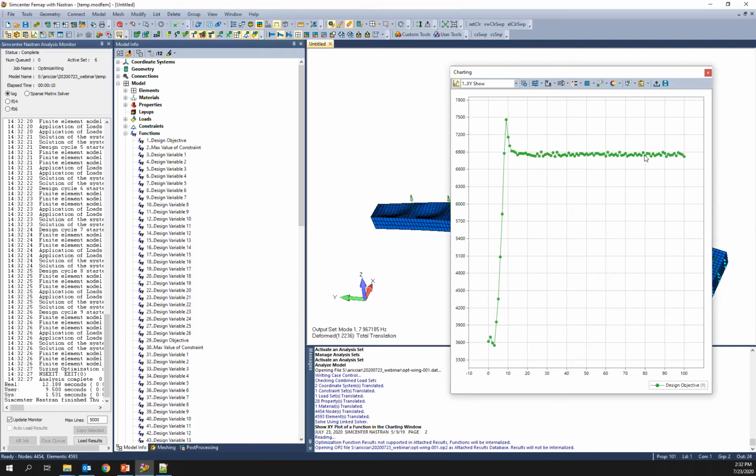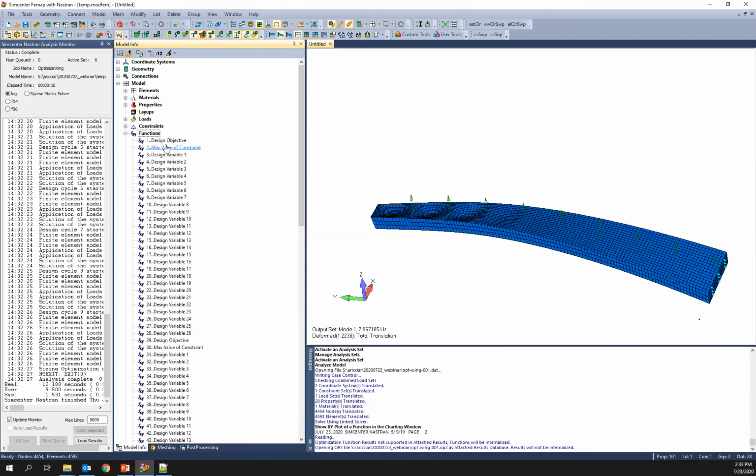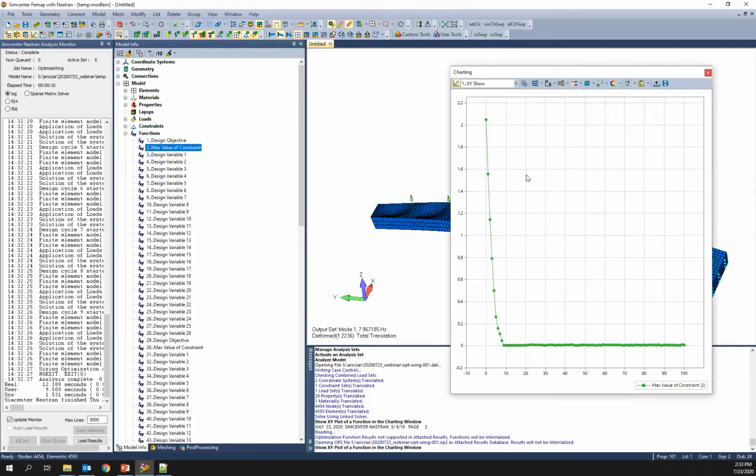There's some noise here, so we probably could have done something to adjust the convergence criteria to maybe not have it run so long, because this noise is causing the convergence criteria to fail. So this is one of those examples where you can start to pay attention to the convergence history and maybe make some adjustments. I might just kill it, run it once and see what happens, and then you see it's kind of converging in 30. So if you know what you're doing, you can play around with different parameters and get the most out of your solves.